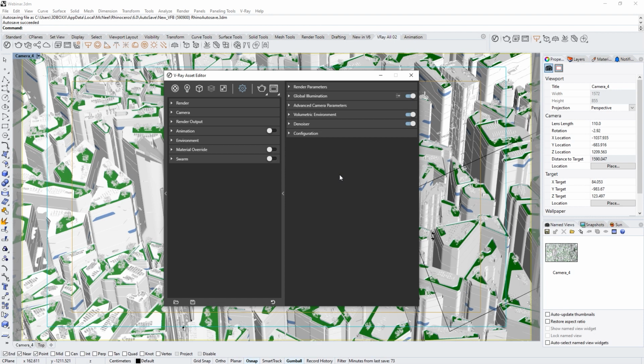I've opened up the scene I'll be using for a production render here. First, let's explore a crucial setup step before we can do light mixing in VRay 5. For a quick background, when a light mix render element is added before rendering, the intensity and color of the lights and light-emitting materials can be changed directly from the VFB, both during and after rendering. This enables you to easily experiment with a wide variety of moods and lighting styles in one convenient location, without having to navigate to individual light parameters or needing to re-render your image.